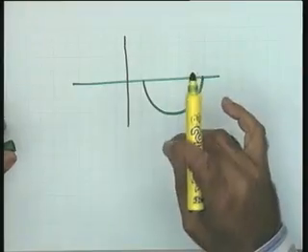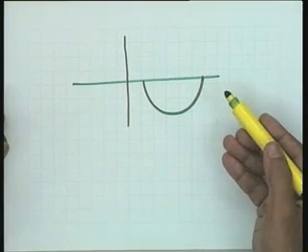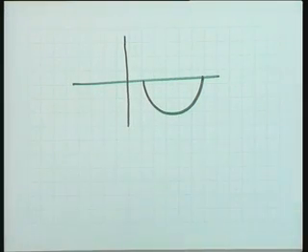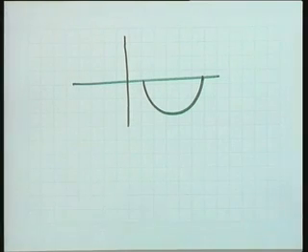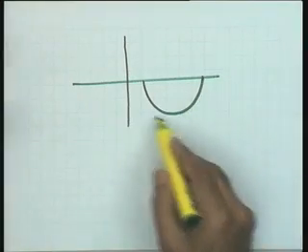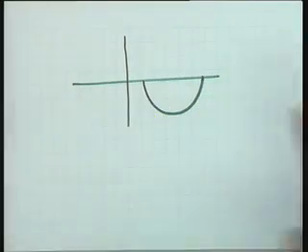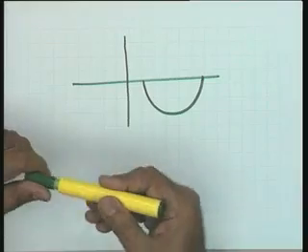However, mathematically, if you apply the logic, what is the phase margin and what is the gain margin in a type 1 second order system? We get gain margin equal to infinity. In this system you will also get a phase margin which will be more than minus 90 degrees. However, the interpretation of that, the meaning of that with respect to closed loop system stability, is not that much. Therefore, for a system which is inherently stable for all values of tau 1 and tau 2, relative stability study has hardly any meaning.